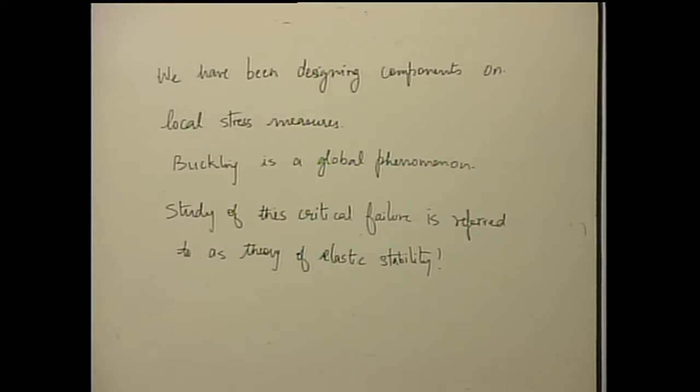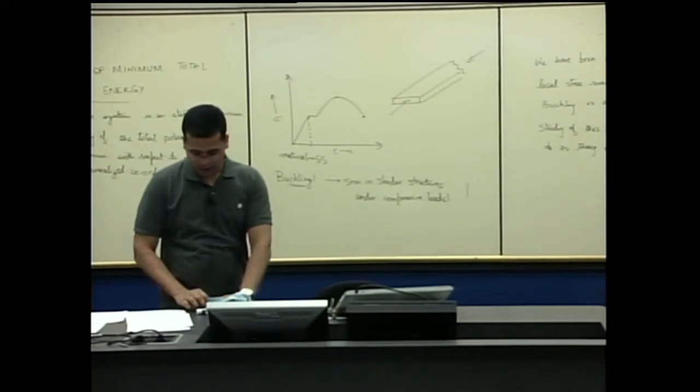So when buckling happens, either it's a divergent phenomenon, which is defined by the second order derivative of the potential energy going negative, or it can be a slightly stable phenomenon, and based on that you might get a post buckling path which is stable. Post buckling path just means that the system has already undergone buckling. So for example, in this case, this is stable. If the external conditions don't change, nothing is going to happen to this cantilever beam.